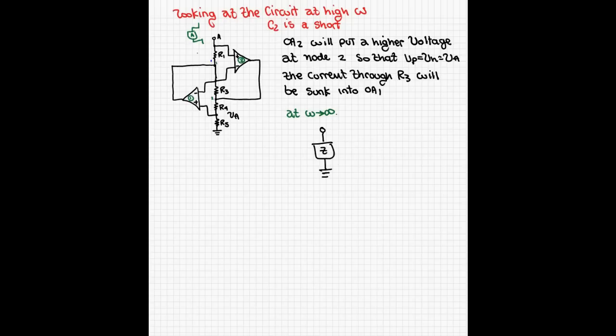Get some C, where the current is going to be equal to 0 because there's no drop across here, since both of them are equal to VA. And then the V looking into A, the voltage drop from this structure, it's going to be VL equal to VA. So at high frequencies, the circuit behaves as an inductor, which is what we wanted.